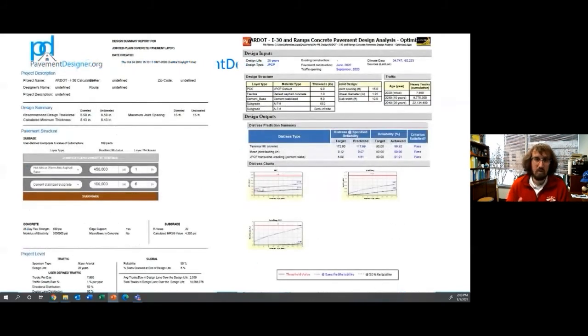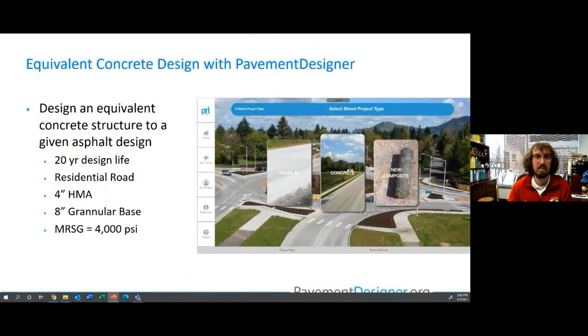I did both of these designs, and with PavementME the cracking is what's driving the design. It's getting closest to failure, but still they only predicted 9 inches of concrete was required. It's great to see those two lining up because they're mechanistic-empirical approaches to pavement design, so they result in pretty realistic numbers.